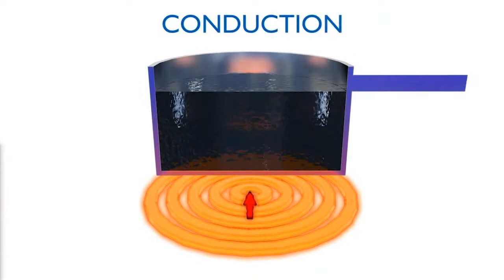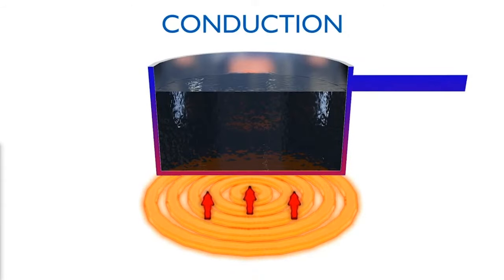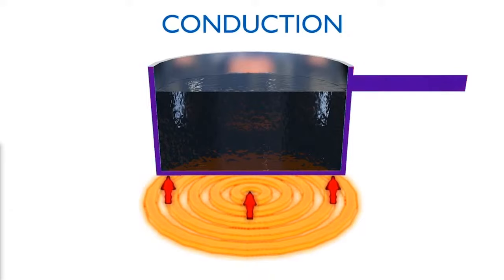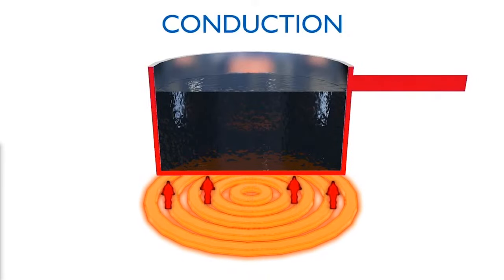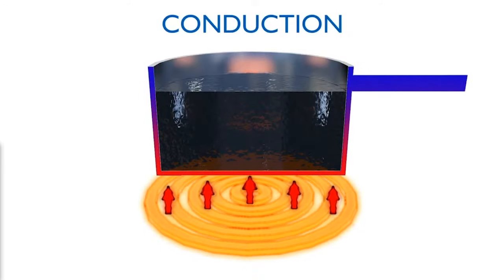Conduction happens where two objects are in contact with each other, like the base of the pan sitting on the hot plate. This direct contact lets the heat flow from the warmer hot plate to the colder pan, until either temperatures equalise or the pan is removed. Most building insulation boards, such as mineral fibre or polyurethane, work to resist heat transfer by conduction.